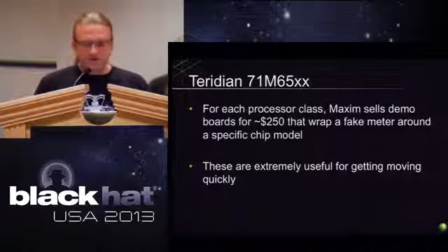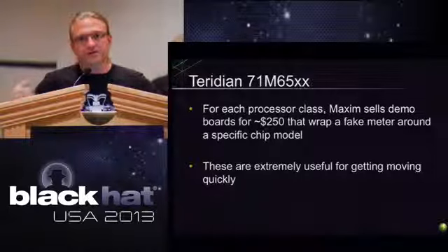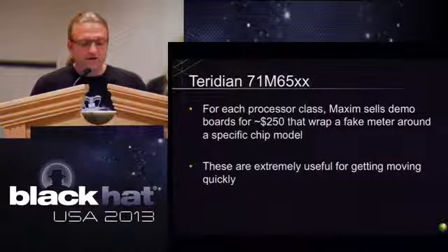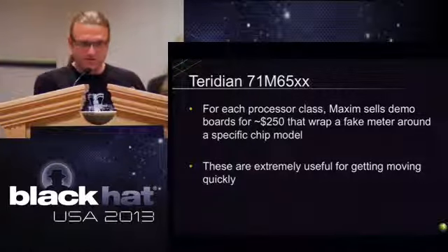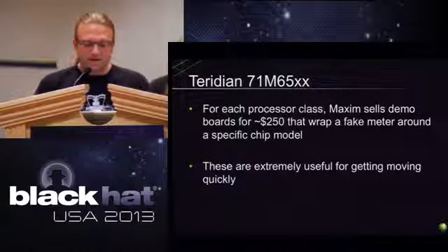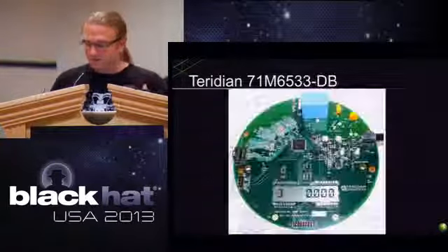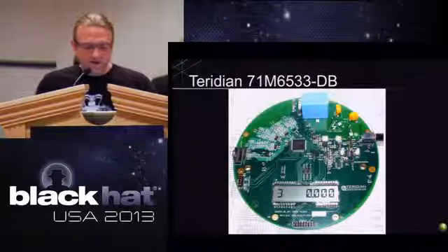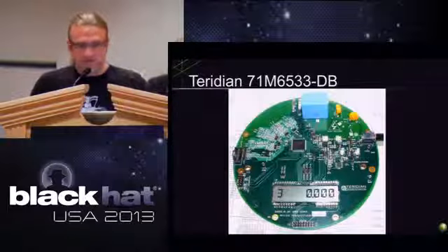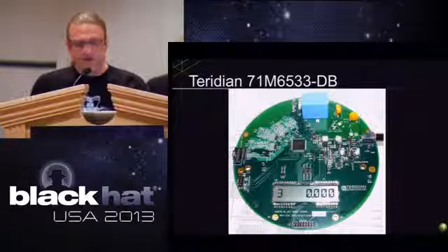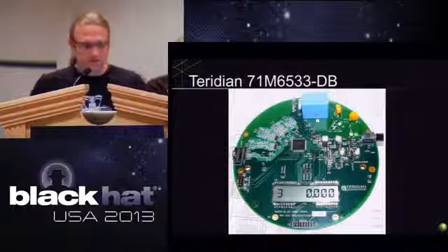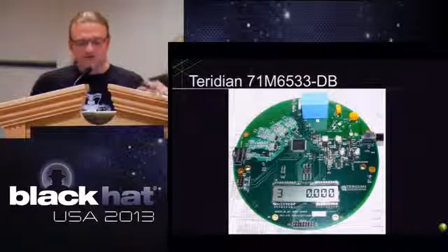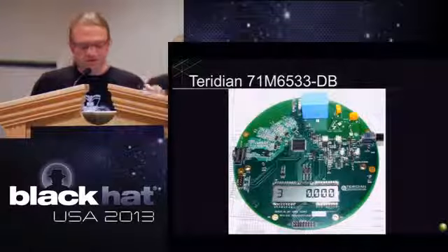I've got nice code so you can start figuring out what the chip is doing, at least as far as the vendor. So then if you have a specific target you're looking at, you at least know what reference they started with. And you can look at the board, which here's a demo board right here. It's the one we're playing with today. But you can start looking at the board and looking at all the specs that come with it and pretty quickly figure out, this is how I physically put the chip into debug mode, this is how I enable JTAG if it's been blown. It's much easier than just starting blind.